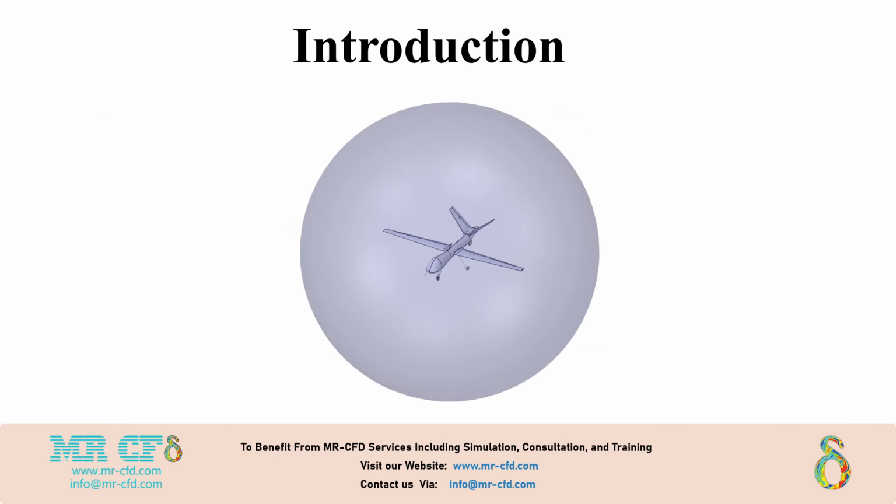In this session of SpaceClaim course, we're going to talk about Enclosure Tool. In CFD modeling, an enclosure is a simple volume you create around your part to represent the surrounding flow thermal domain. In SpaceClaim, the Enclosure tool quickly generates that wrapper, a box or cylinder, at specified clearances around your solid.